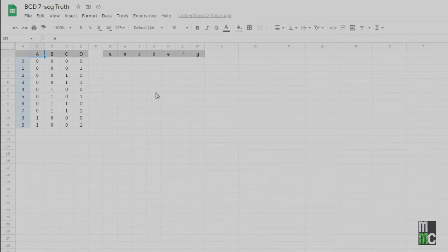And so what we want to do is go through all of these and say, okay, for instance, the output of 0, all zeros, which is A, B, C, D all zeros, we want a 0 on the 7 segment. So a 0 is everything but the G. So I turn on all the segments and I leave G off, like this. And we want to continue doing that. We take number 1, for instance: A is off, B is on, C is on, and everything else is off. And we just want to continue to do that.